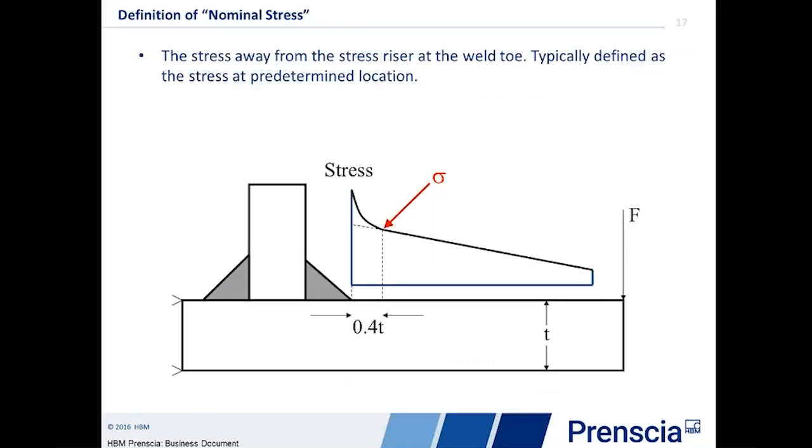These all have the goal of trying to measure the load going through the weld in something that is normalized, hence a stress, yet eliminate the discontinuities at the weld toe. The initial one is the nominal stress method, one of the earliest, and originally it was probably a strain gauge at the toe of the weld. But here what we're looking at is trying to measure stress at some distance from the weld toe, ideally picking up a stress that isn't the discontinuity at the weld toe. One issue with this is that it tends to be quite mesh sensitive, obviously, if we're applying this on an FE model.